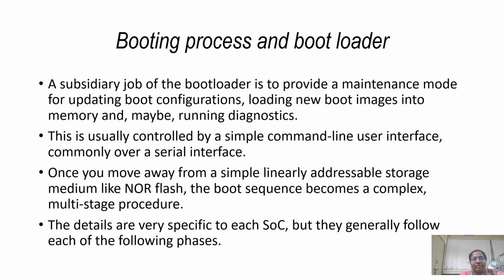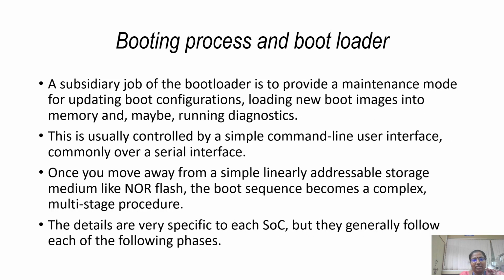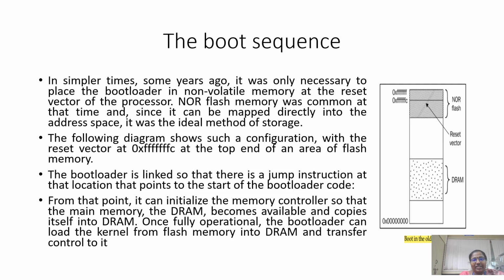Once you move away from a simple linearly addressable storage medium like NOR flash, the boot sequence becomes a complex multi-stage procedure. The details are very specific to each system on chip, and generally they follow phases. If you are using any flash memory, NOR or NAND flash or managed flash, you will have a boot sequence.